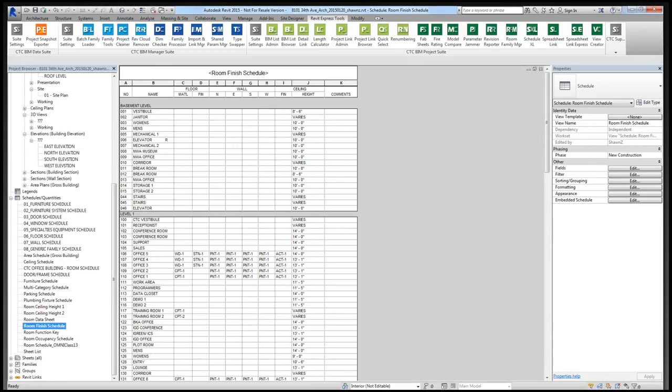In fact, you can even do concatenation. You can do formatting of multiple strings pulled together. So if I wanted to say, for example, in the electrical voltage parameter that's pre-existing, that's text, I could say with a text string, it's 208/120 parenthesis 3 or parenthesis 1 or whatever I wanted for different phasing. So I could actually fill out that voltage text string with something that way using, again, Excel and formatting it from other properties on an object. So similar to what I'm doing here for the interior design, the ability to pull in either text or a value from someplace else, or again, I could combine them together. I could actually list multiple ceiling heights here if I had a way of obtaining that information.